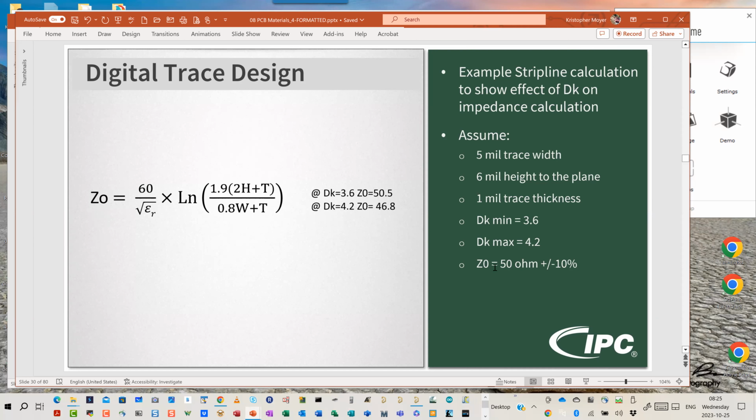So is it safe that to achieve the 10% tolerances, 5 mils is kind of the limit? I've done plus or minus 10% on 5 mil for 30 years with never a problem at a fabricator. Below 5 mils is where they started balking a little bit. Gotcha.